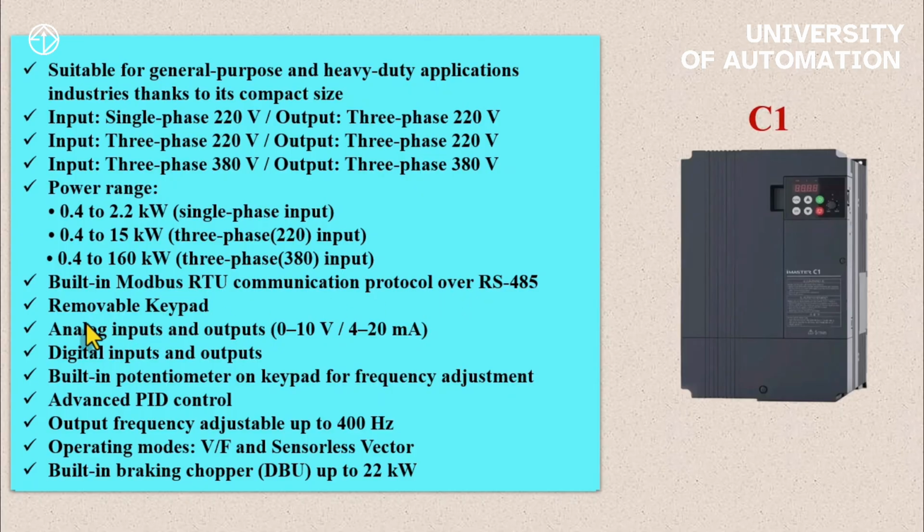The keypad on this inverter is detachable. It has analog input and output, both in voltage mode and in 4 to 20 milliampere. It also has digital input and output. You can use each of the digital inputs for start, stop, fault reset, emergency, and other functions. You can also use the relay of this inverter for various applications.